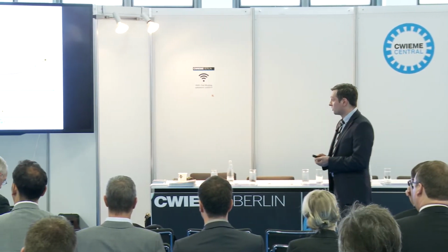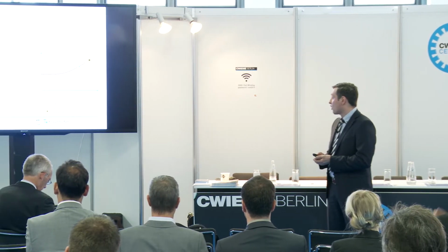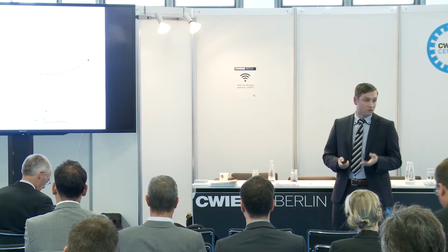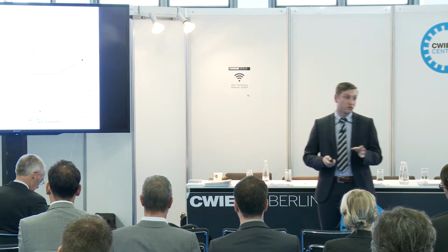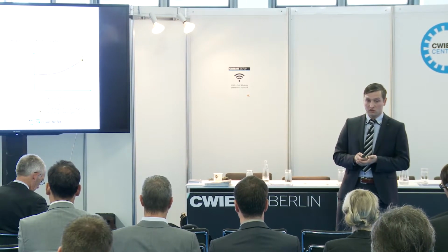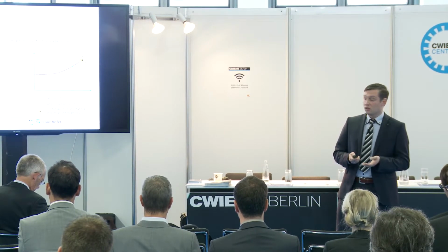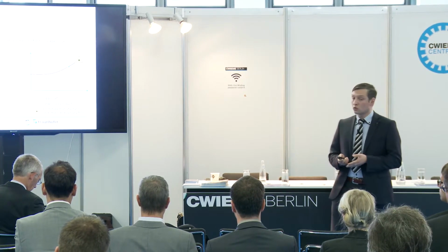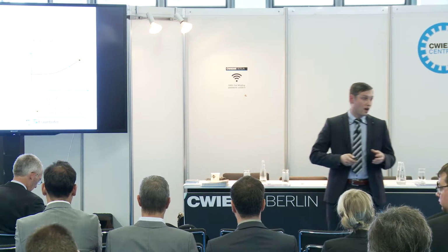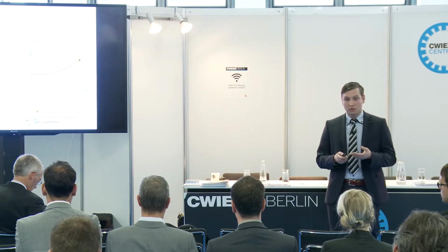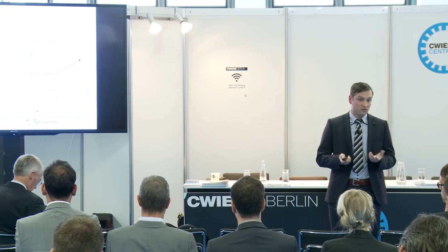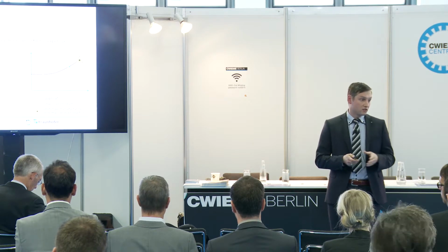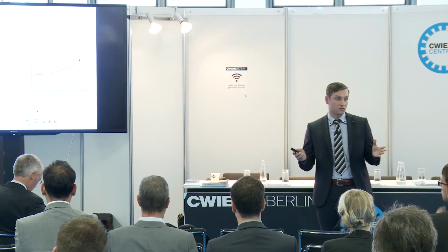In the case of cost reduction, usually mechanical punching is used for large-scale production rather than for prototyping and small series due to high tooling costs. On the other hand, laser cutting is favorable in terms of prototyping due to a high flexibility of processable material grades in terms of gauges and component sizes.